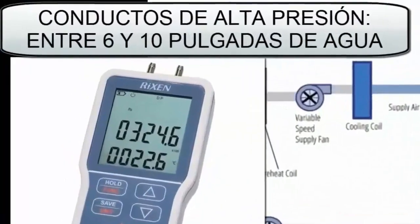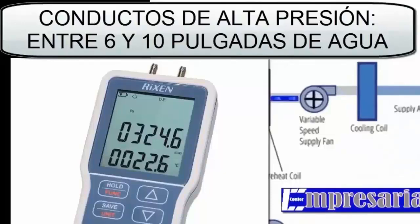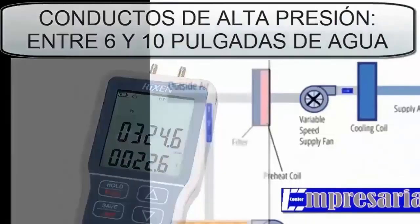High-pressure air ducts are systems with pressures between 6 and 10 inches of water column. Static pressure is generally limited to a maximum of 7 inches of water column, and duct velocities are limited to 4,000 feet per minute. Systems that require pressures greater than 7 inches of water column are normally unwarranted and could result in very high operating costs.